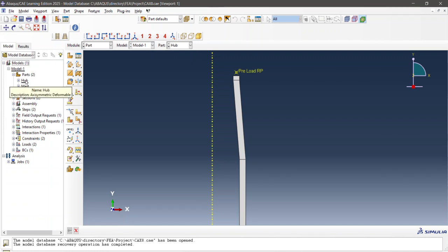Now, I decided to model everything axisymmetrically. One, it allowed me to do it in 2D. Two, it lets me take advantage of not needing to use so many nodes. To model all that would be massive. So even just doing the hub and the mast, which I roughly did to scale based off memory, based off some pictures, and just my experience with them, I backed out a rough shape and rough dimensions of what this interface would look like.